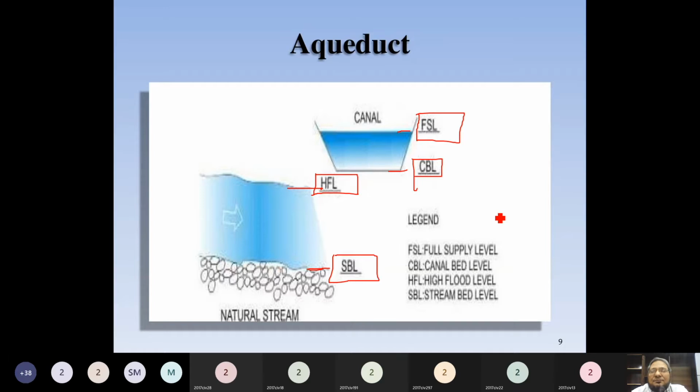Are you sure? क्या ख्याल है? Yes sir. तो वहां पे जो बैठा है head regulator of the main canal में, उसने 80 millimeter से जो stage लाने के लिए जितना discharge चाहिए, so he has to reduce that discharge. Okay, so proper regulation of the barrage is required, and also the head regulator of the main canal.